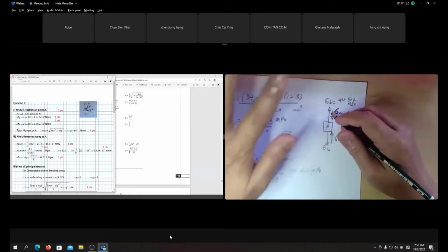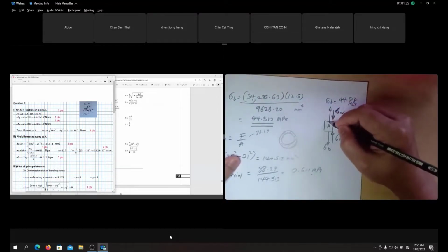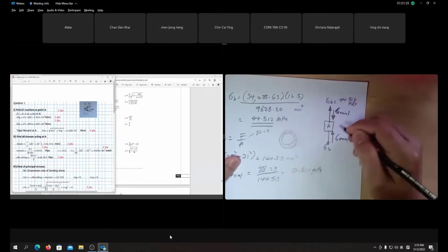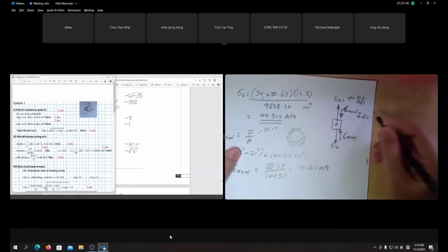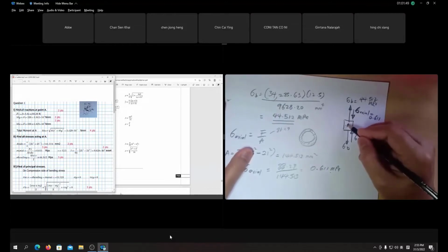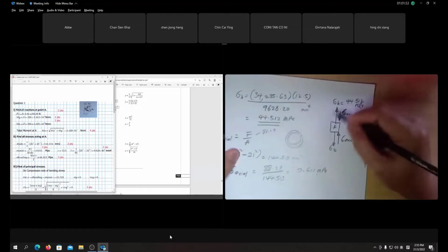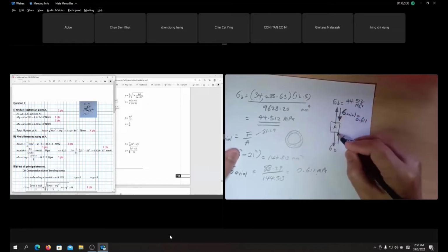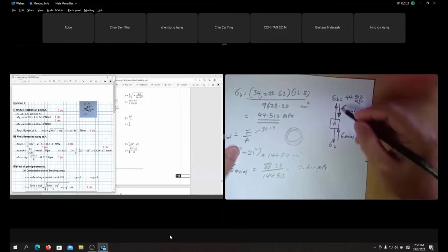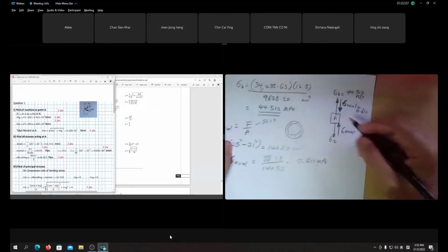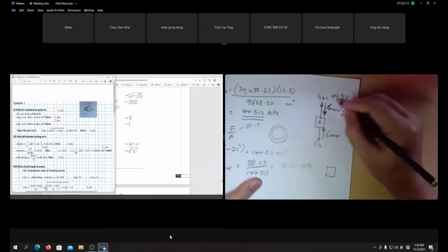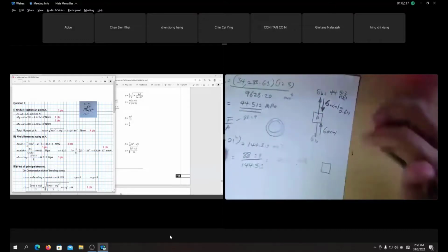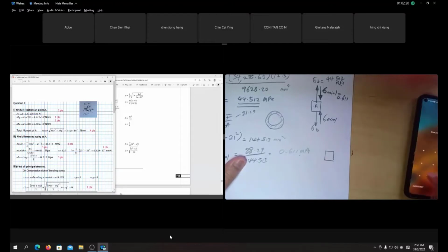So for the element at A, I go for tension. We have two cases, one tension side, one compression side. For the tension side, bending produces upward because of tension. But from the direct force, the axial stress is 0.611, which goes compression. So the total stress at A in tension has been deducted. Understand, class? Here, tension is greater, 44, but we have to subtract the axial, because axial already compressed it.